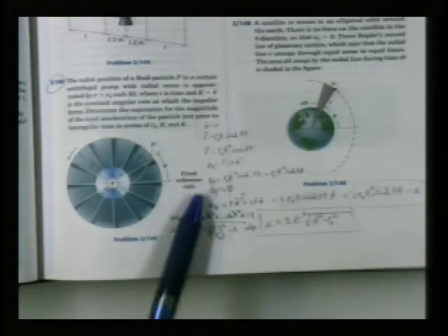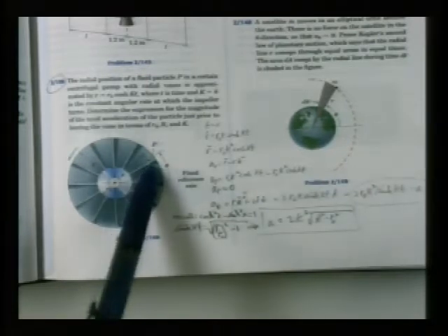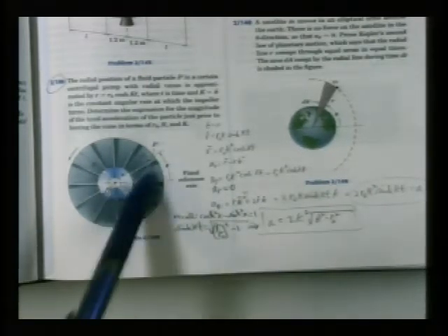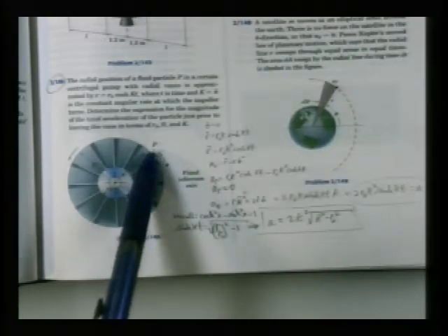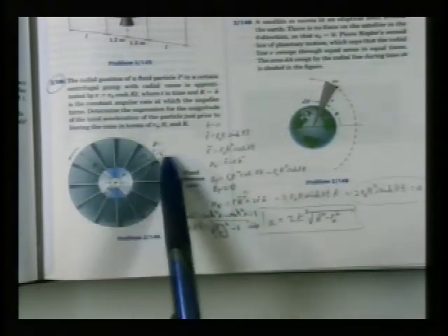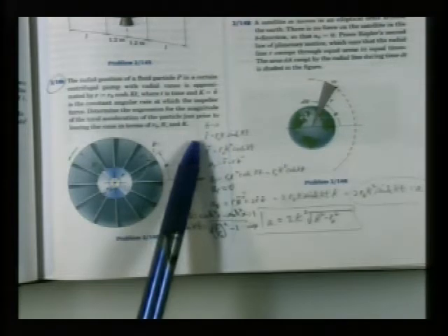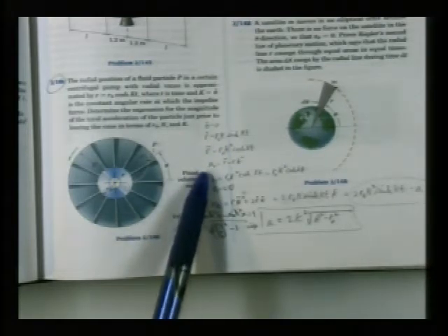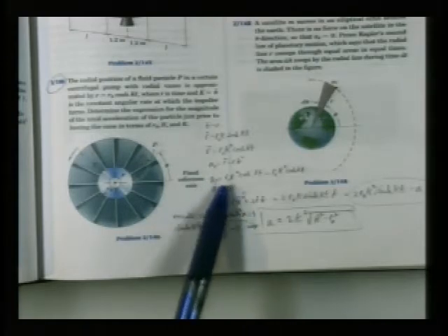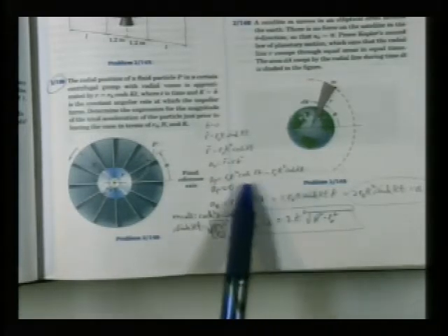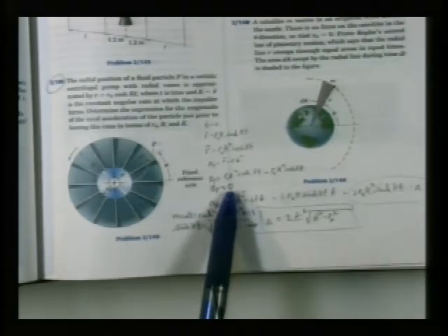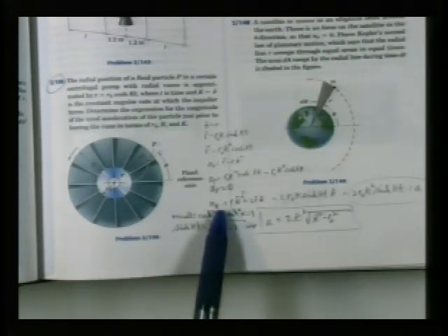What happens is this particle, the water flows in and then it starts to move outward as it comes in contact with the fin. And as it moves outward, we're supposed to figure out what the acceleration's magnitude is just as it reaches the capital R radius, shown here. So right when it's on the outer edge here, what's the magnitude of the acceleration? We went through the calculation with the hyperbolic function, and the radial acceleration turned out to be two terms which went to zero. So there was no radial acceleration, there was only theta-directed acceleration.